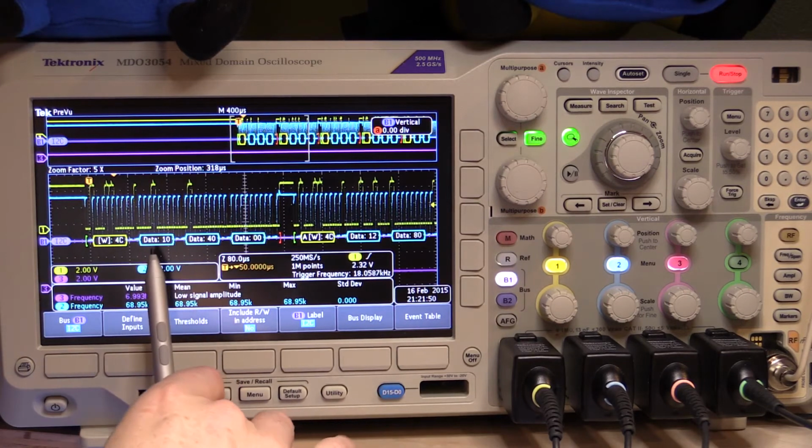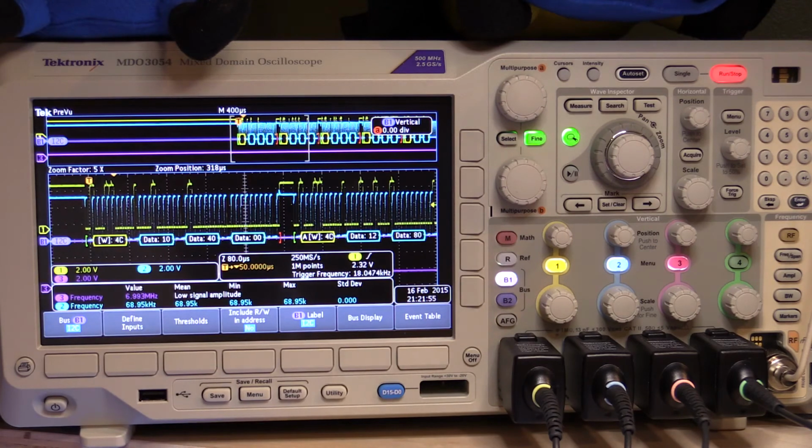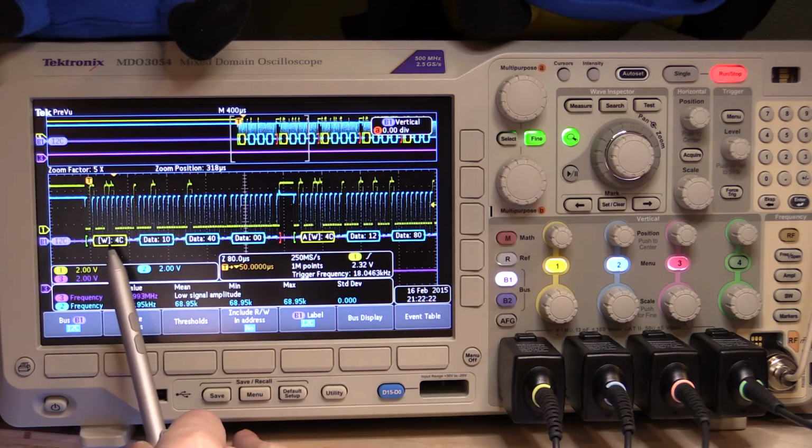And we are sending out, if I read off the code there a second, the first thing we send out to the controller is 10, then a 12, then a 14, then a 16. But in between that, we're also sending out the different values. So 4000, 8000, C000, and FFFF. So if we look at this on the oscilloscope now, let's just take it as being address 4C.